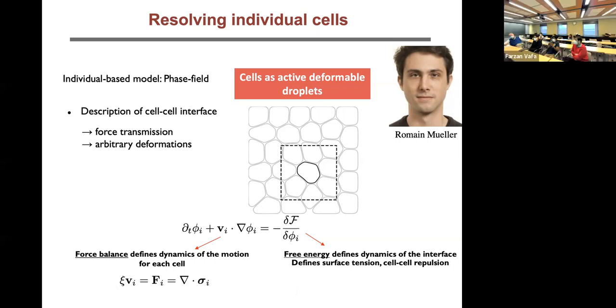So sorry, another question. It looks like you're assuming an incompressible velocity field. You're taking the velocity out in front of the gradient there. That's maybe approximately true, but if there's extrusion into the third dimension, you'd think there would be sources and sinks, and so there would be a non-zero divergence. Yes.